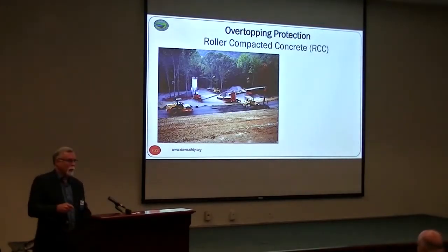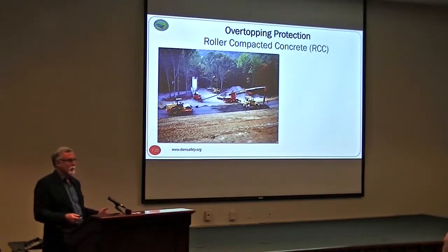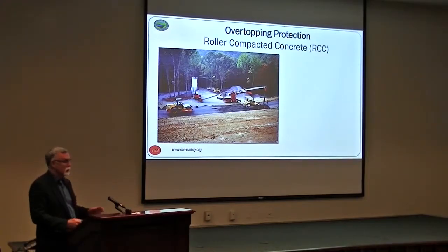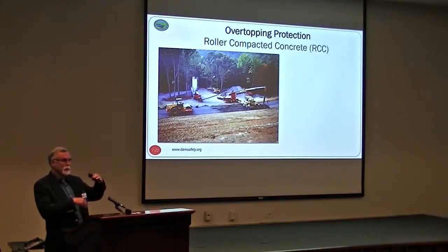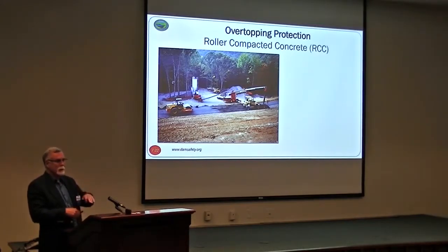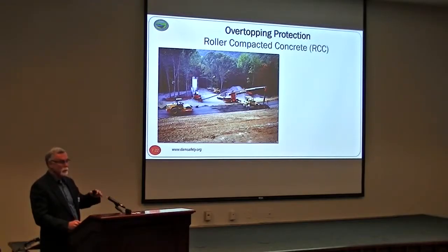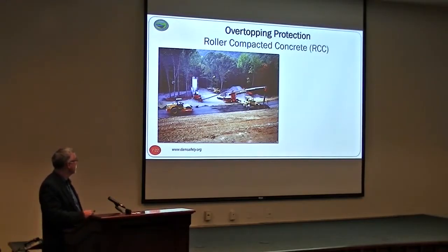To show you before, if you really need a lot of spillway capacity, sometimes you just make the spillway over the dam. And that's been done quite frequently. There's a couple of processes I showed before. You use a roller compacted concrete, but you've got to have an area to do it because you're going to make that concrete generally on site. So here's a plant that's blending the aggregate with the water and the cement. They use a conveyor belt, and here they are placing the concrete. It's placed in 12-inch thick layers, usually one layer on top of the other.